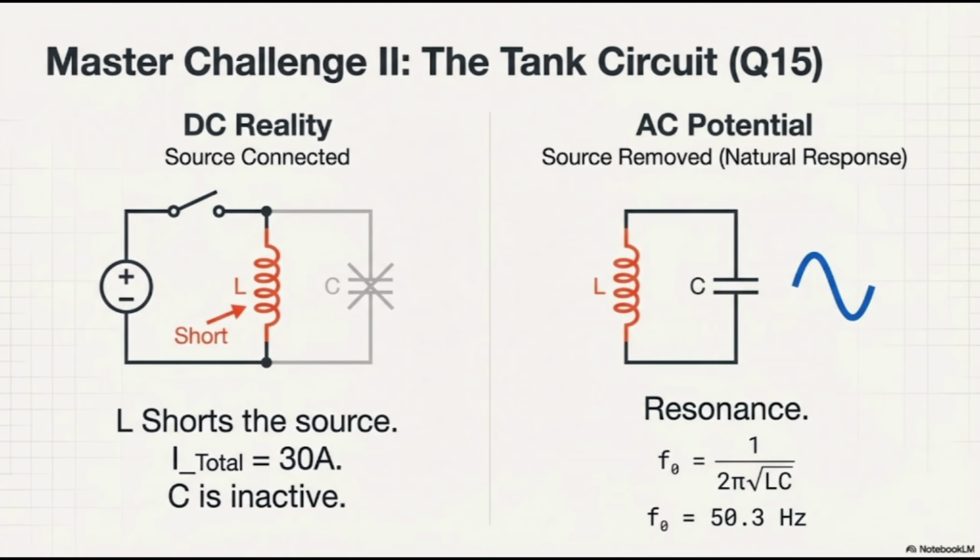This question is so important because it leads to a very important concept in itself, the resonance frequency. So what is the resonant frequency? Resonant frequency is the point where your capacitor and inductor have the same amount of reactance, and they can simply cancel out each other. What is reactance? Reactance is a concept that you would face while you're working with AC circuits, because in DC circuits it doesn't make sense. X of C is 1 over 2 pi F C. This is the reactance for your capacitor, and X of L is 2 pi F L.